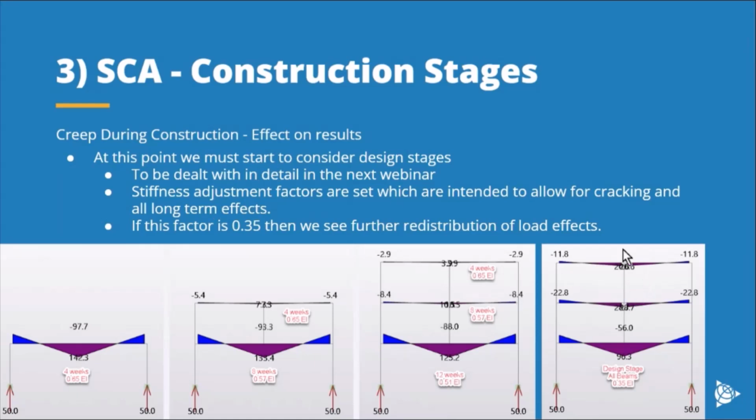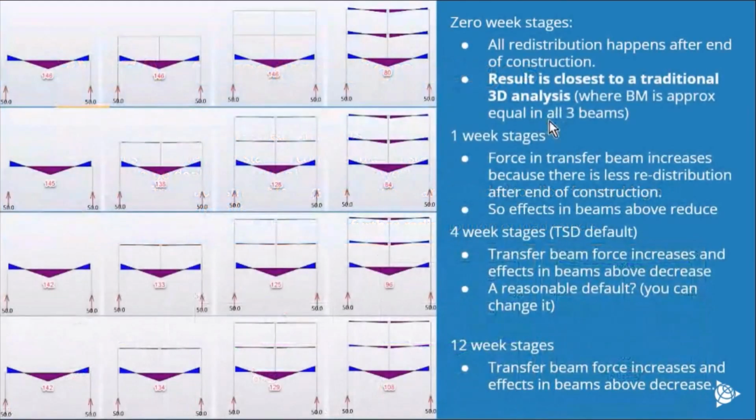Talking about the design stages in detail is again the subject of the next webinar, but it's very hard at this point to separate the topics of construction stages and design stages when ultimately you're interested in what happens at the end of the design stages. So let's think about variations of this now, where I've got 0 week stages, which effectively gets rid of any creep during construction, 1 week stages, 4 week stages, and 12 week stages.